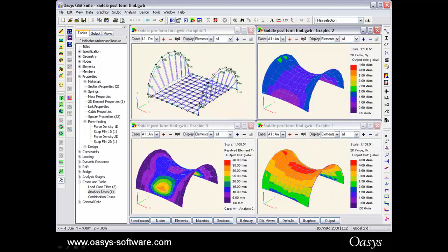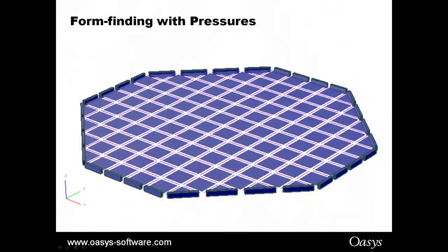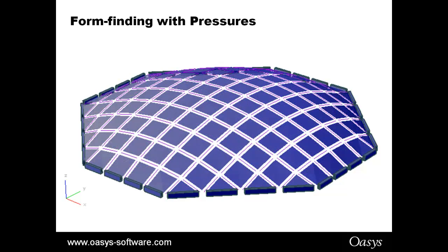Now, that was a cable edge. This is a mixed structure, so we've got to form a saddle, so we've got two rings which are the fixed edges, and note during the form finding they're fully pinned, and the other low edges are cable edges, therefore they are free. You can include pre-stresses or forces in the form finding. I mean, if you're doing something like ETFE foil cushions, you include a load within the form finding to then find the pre-stressed shapes.